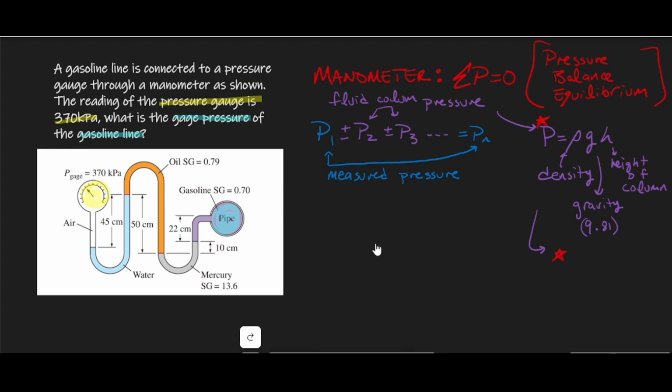Quick tidbit, you see that SG of the fluids in the diagram? That's specific gravity. It's just a cheap way for the writer to try and wreck you. SG is density divided by 1,000. So take each SG and move the decimal to the right 3 spots to get the densities. As soon as I see SG, I just convert it immediately.